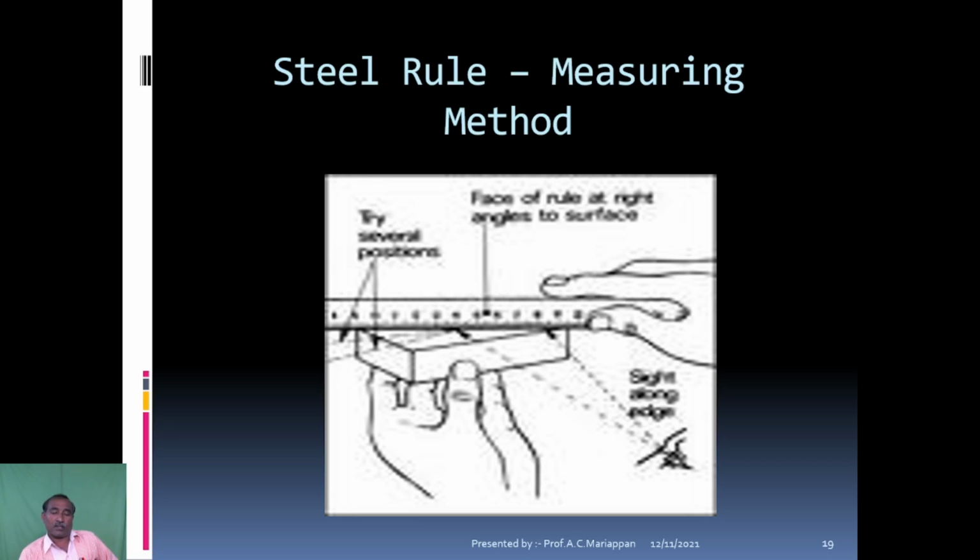So our sight vision usually, 150 mm minimum distance and maximum of 300 mm distance, is the vision sight considered for oblique vision to measure any kinds of objects as you see in the picture. So for linear measurements, we consider leaving a certain distance from the beginning, because by using it continuously the edge of the rule may be damaged.